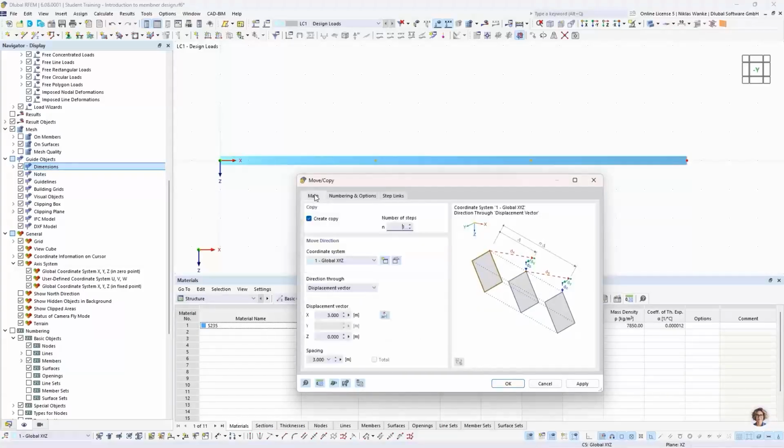One thing I probably forgot to do was the displacement vector. So we want to displace the node 1.4 meters in negative Z direction. So it has to move to the top, and the positive Z direction is directed to the bottom.